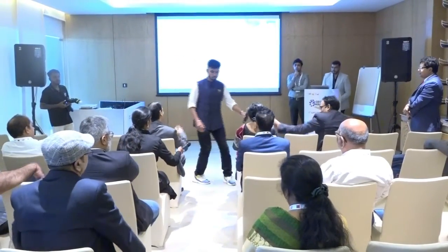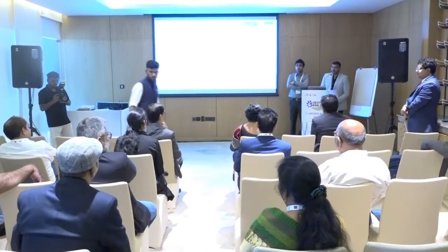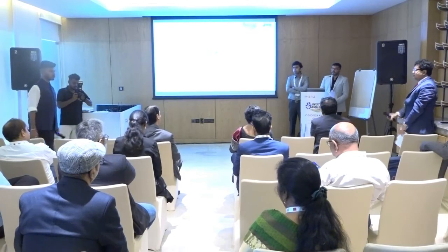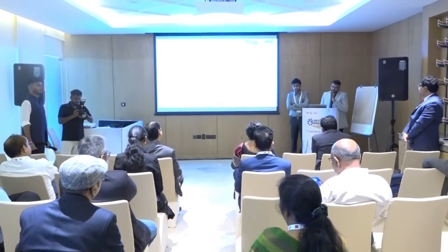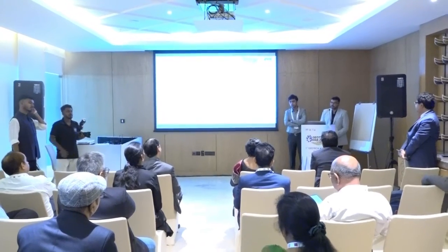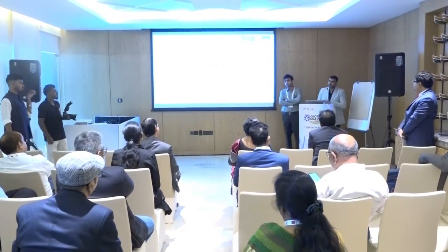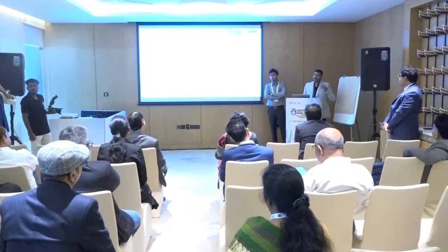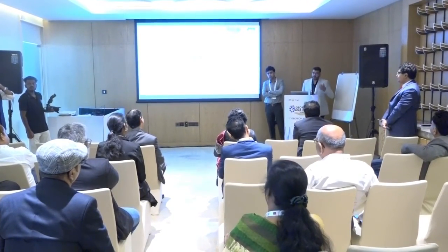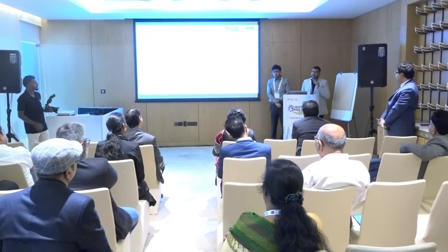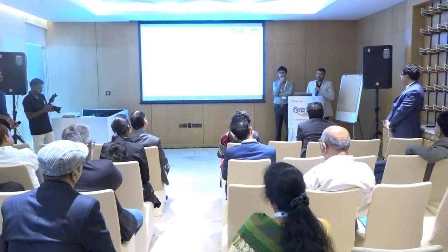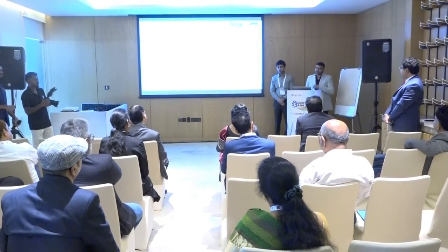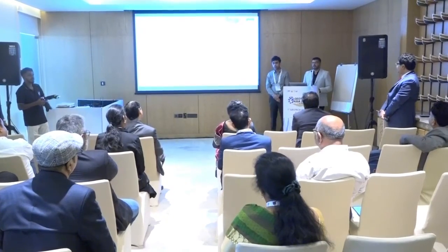I just want to know, any limiting settlement you have considered, or is it given by the designer? What is my limiting criteria? How much settlement is allowed? No, we have considered a settlement of hardly 2 to 3 mm in this design. In our design, there was no settlement given, but as we have to execute the work and open the face, when you open the face there will be a slight settlement in your soil. So in the design we have considered 2 to 3 mm of settlement, but however, during the construction, we didn't find any settlement.